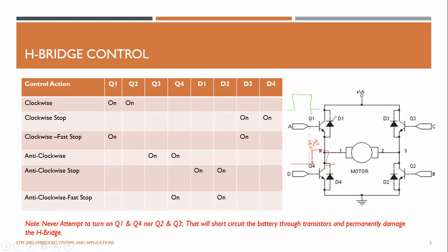So then you know 100% these two guys are not turning on at the same time, because the signals start from somewhere here, not here, right? There's no overlap between two signals, and then we are pretty much sure Q1 and Q4 are not turned on. Same thing applied to Q3 and Q2. Otherwise, the H bridge will be destroyed and you can no longer use it.